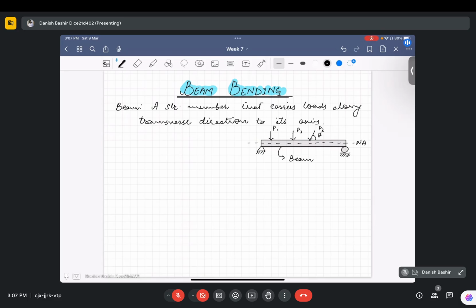In structural analysis, we have seen a number of methods of analyzing a beam. For a simply supported beam, we first find the reactions at the supports, and then we compute the shear force and bending moments at any section. A similar type of analysis can be done here in the finite element method. But as I already told you, the beauty of finite element analysis is that it can incorporate complex boundary conditions.